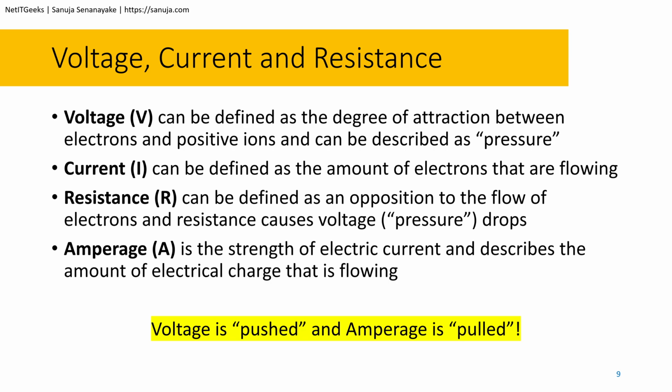There are ways that this is now mitigated in certain situations, where you can use a device rated for any voltage, for example with PoE applications, power over Ethernet. Let's say your power over Ethernet injector, or the switch ports on your router or switch, are rated for, let's say, 24 volts, but your device is only 12 volts. What happens is the device negotiates with your PoE port, saying, hey, I only need 12 volts. I don't need 24 volts.